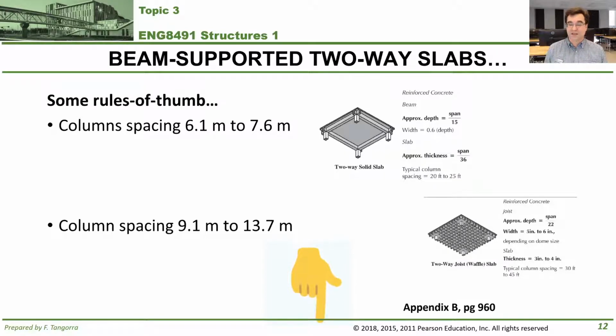But here's the thing, the cost skyrockets because there's a lot more work involved with doing a slab like this. Typically, these slabs are not made anymore. They're not built like this anymore in Canada. It's too expensive, especially given that you can get the same result by simply readjusting the reinforcing, slab thickness, and the location of the beams. Okay?